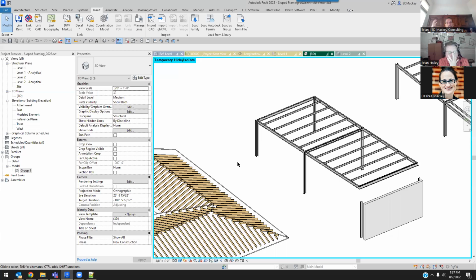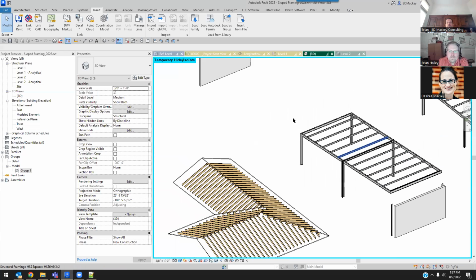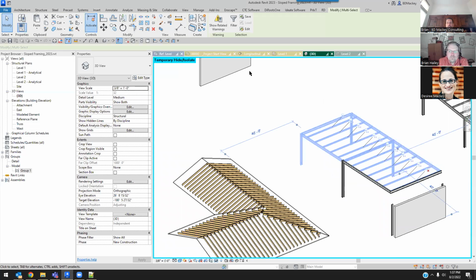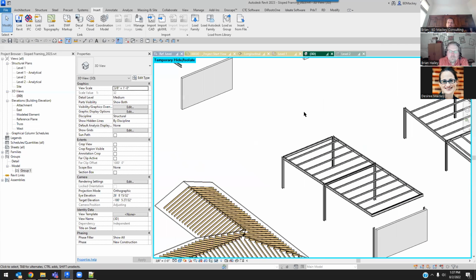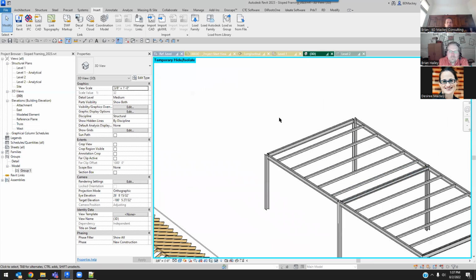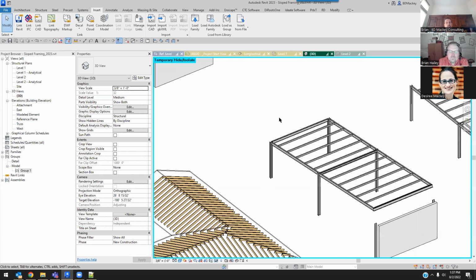So yeah, you can, but like I said, the amount of finessing I have to do with dealing with groups, I feel like I can do one floor, grab everything on that floor, copy to clipboard, paste to the new floor just as quick as I can deal with jacking around with groups. If something changes, I delete it, I copy it up, I re-tag it, and I don't do dimensioning on every single floor plan. And especially as things are changing, that's just been my workflow. Again, I'm not in the industry every day, so Courtney might be telling me, hey, this is stupid.